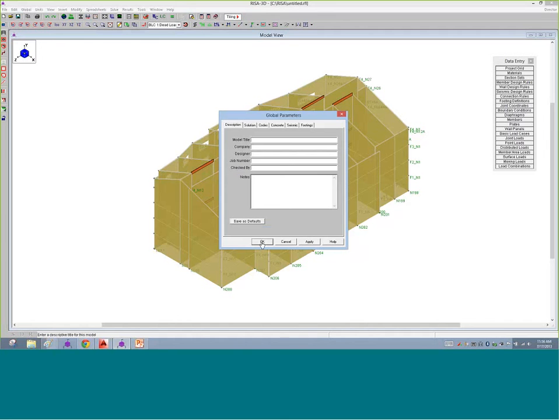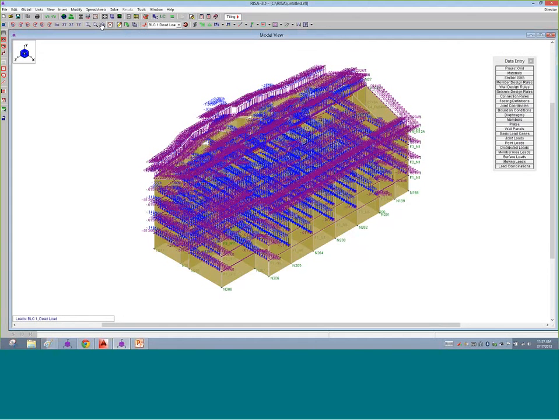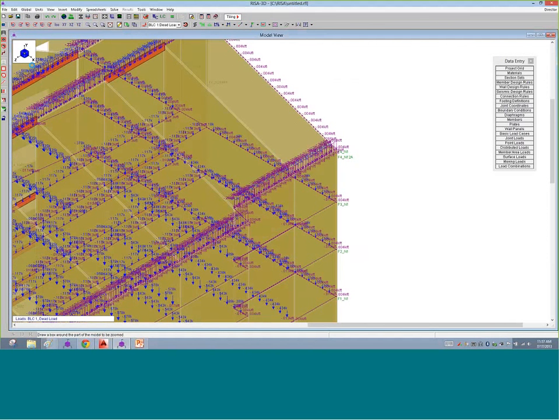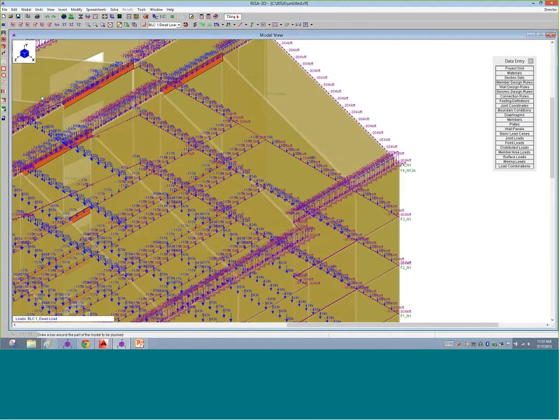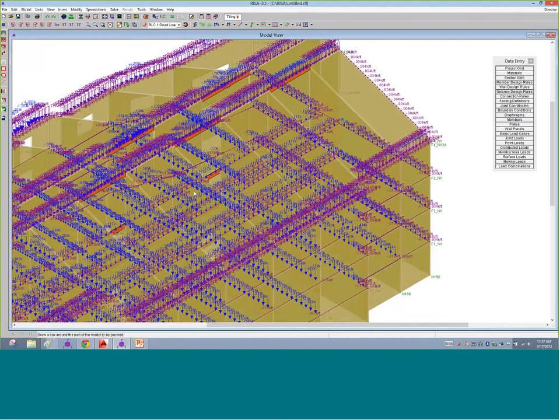What you'll notice is only the wall elements come across, and those collector elements. The other parts of the structure are gone. Now, they're still back in RISAFloor. Don't worry, we didn't lose them. And what's great about it is that whatever they were contributing to the structure is still there. So we had point loads from beam elements, we had all sorts of dead loads coming down on the structure. All of that I'm displaying right now is still on the elements. So we're still seeing those dead loads being attributed to the elements that we're designing currently. We're just not having to bog our model down with a lot of extra elements.